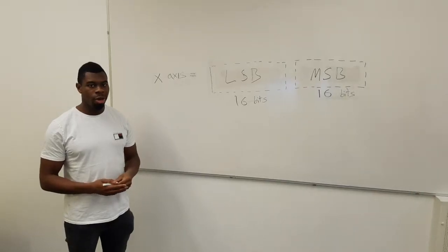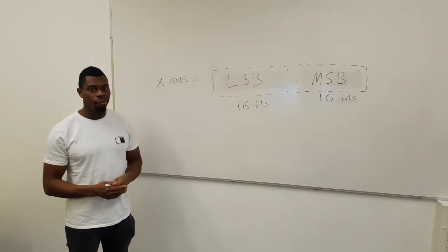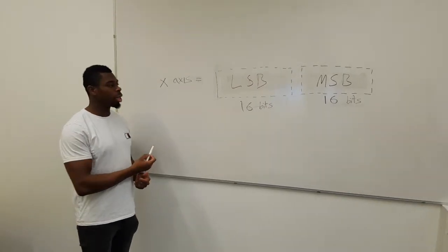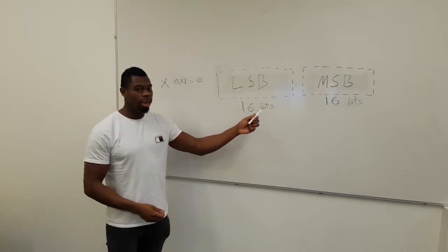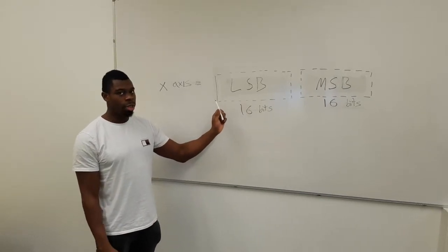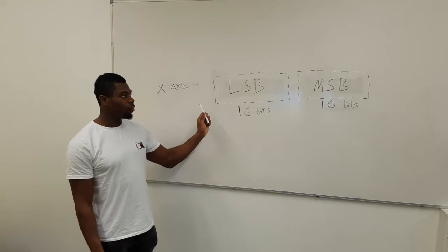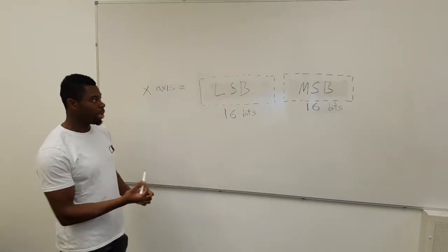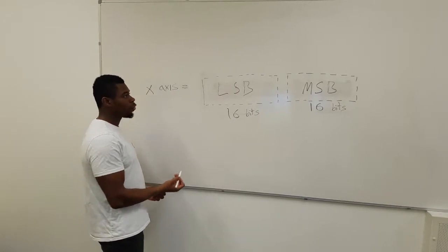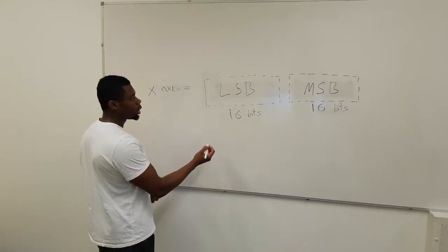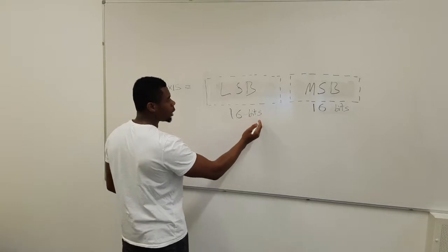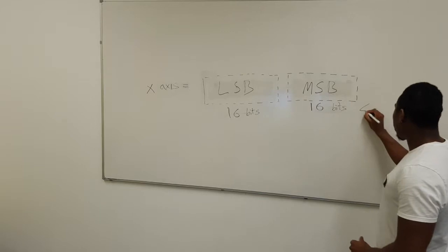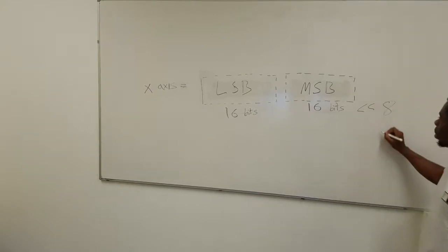So once we've received the data value from the sensor onto the Odroid, essentially what we discovered is it comes in this particular format where the least significant bit is situated on the right side of the full value and the most significant on the left. So to make it a bit easier to transmit across to our base station and to read the values in the correct format, what we needed to do was essentially shift the most significant bit to the right by 8.